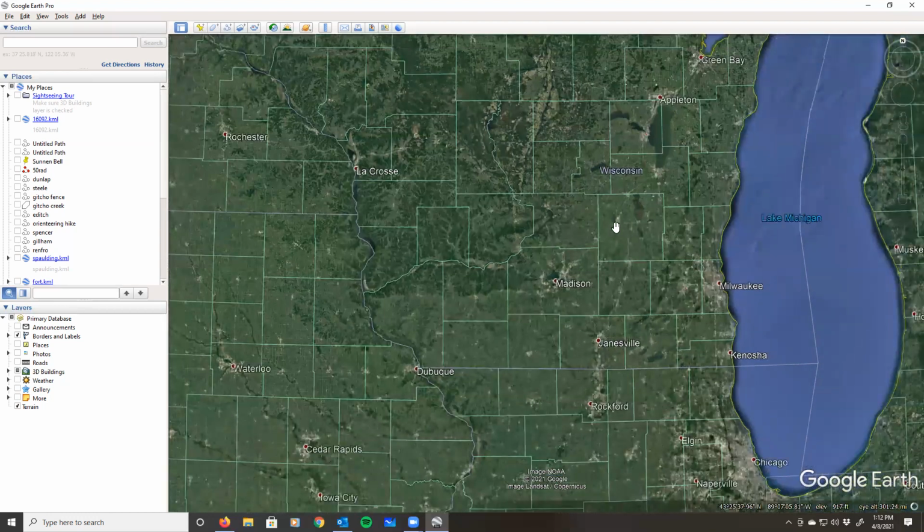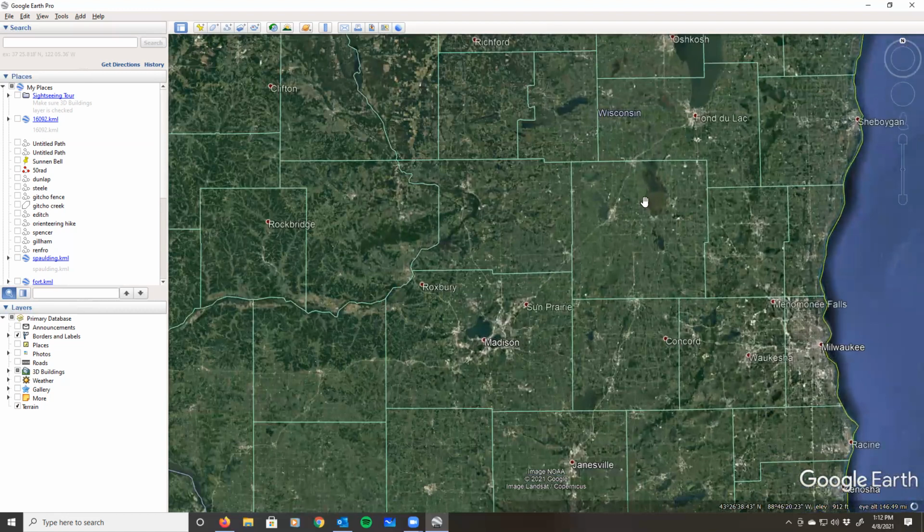The advantage of that is that with each county, you are dealing with a smaller area, so the scale factor is much closer to being 1.